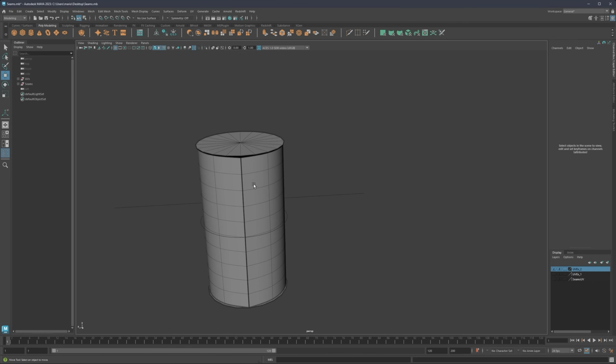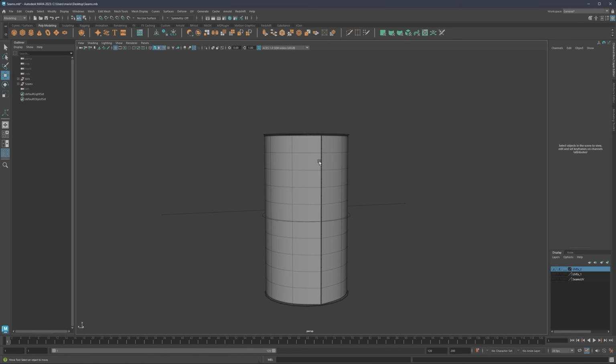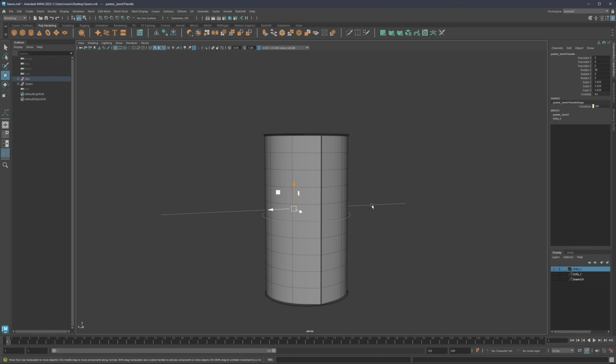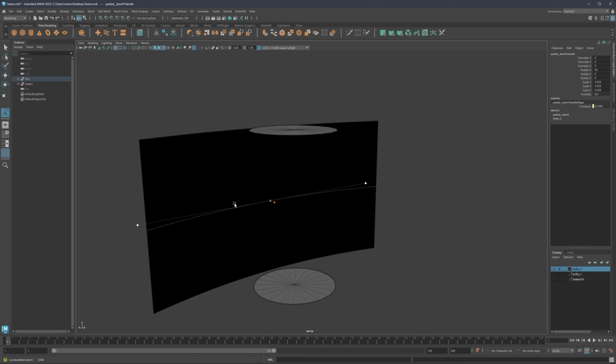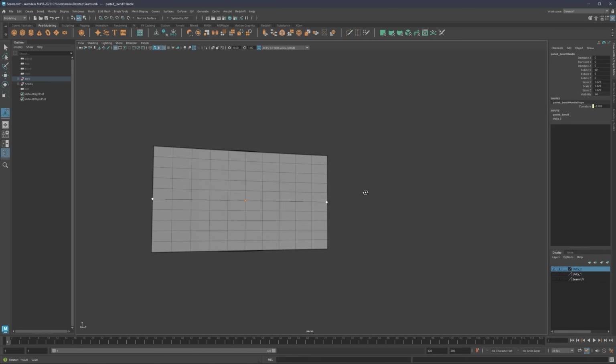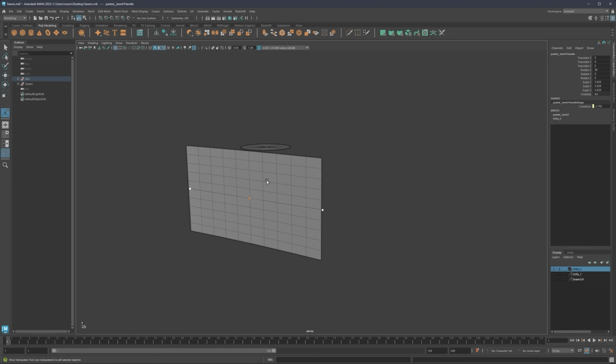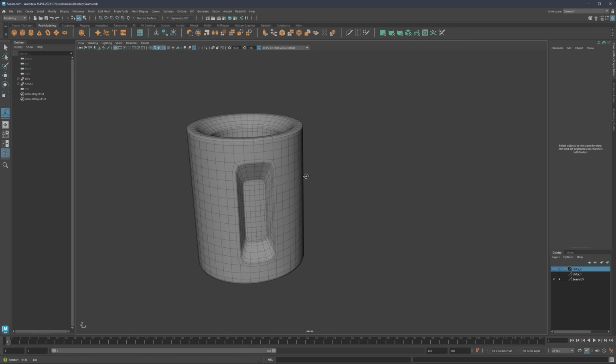We need to cut on the cylindrical parts. We need to have a cut somewhere to flatten it into 2D space, so that from that cut we're able to flatten it out. So on any kind of part, there needs to be a cut somewhere to flatten it out. And in our case here, we're also going to need to find a cut.